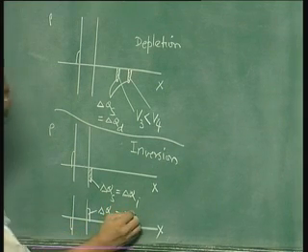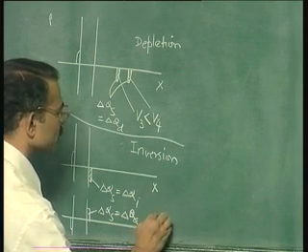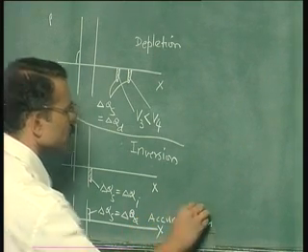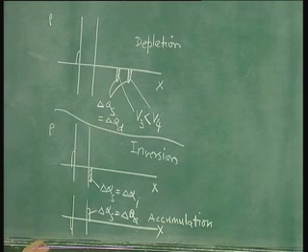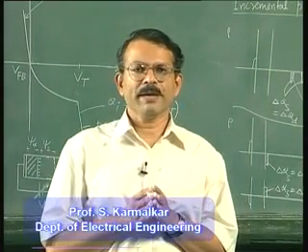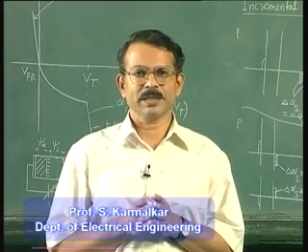This is accumulation. So that explains the qualitative behavior of capacitance as a function of voltage at low frequencies.